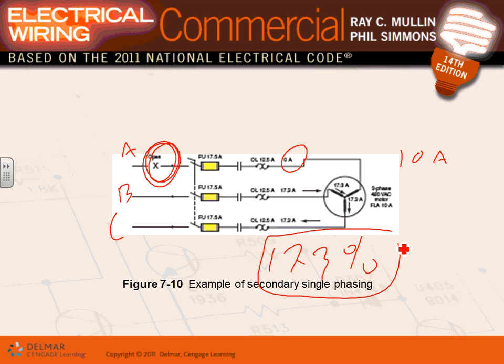Here's how it goes. In a three-phase motor, if you lose one phase, to compensate for the loss of the phase, every other phase will be carrying 173% of what's rated for. Does that make sense? So, for example, this was a 10 horsepower motor. Now this is carrying 17.2 and 17.2 instead of carrying 10. Why? To compensate for the loss of the other phase, and the motor will continue to run.